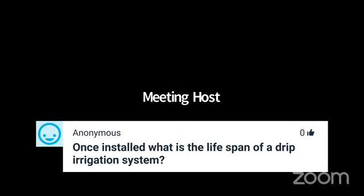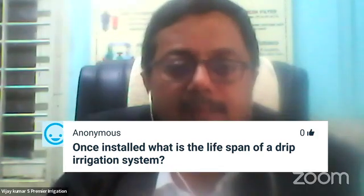Okay, I move on to the next question, sir. Once installed, what is the lifespan of a drip irrigation system? Yeah, a well-designed drip irrigation system, as per the Government of India, should last you a minimum of 5 to 7 years. We have systems which have been working for more than 10 years, but the basic point you have to remember is, it's not that I give you a drip system and it runs forever. The main challenge in the system is that it could get blocked because of the salts. So frequent maintenance of the system by acid treatment or chlorination will be required.